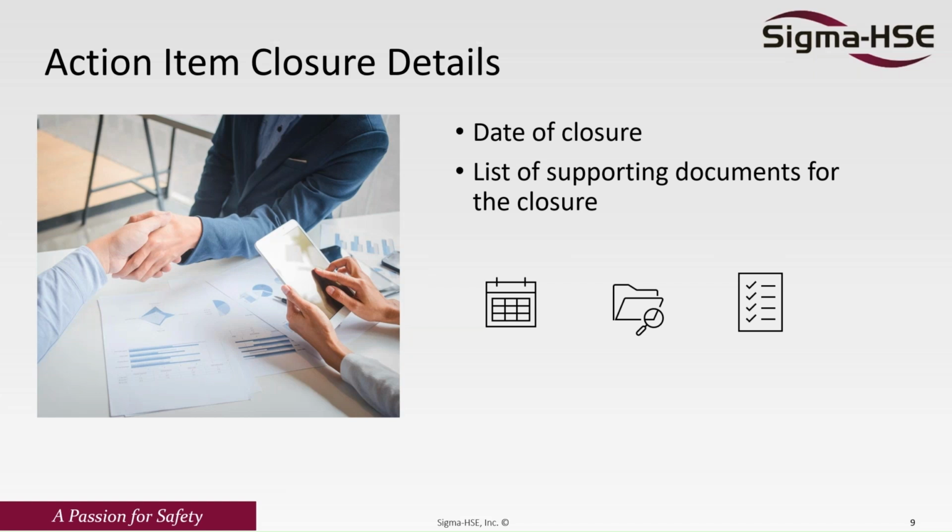If it's something as simple as adding valves to a lock valve program or a car seal program, list your site's car seal or lock valve program and just make sure you have proof that you have closed it. You don't want to just say an action item is closed and have nothing to show that validates its closure.